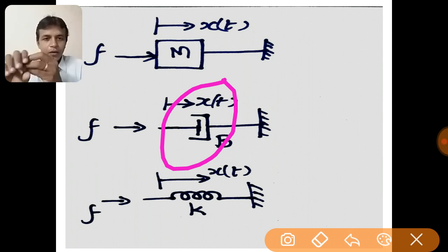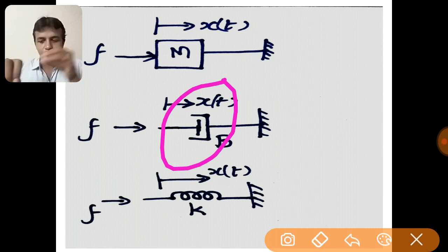When the person releases the door, the piston cannot move very quickly all of a sudden through this gap, because the viscous fluid is there. So it moves very slowly, and due to this the door also shuts very slowly.